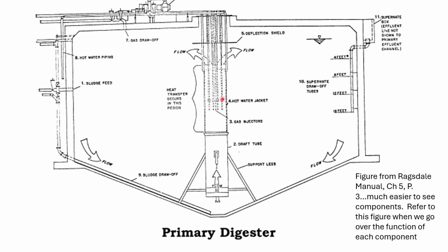Okay. But we also have a heat exchanger here, and that heat exchanger is what's keeping us at our optimum temperature range. But remember, if we misoperate this and we go above 130 degrees Fahrenheit, what's going to happen is this sludge is going to cake onto the heat exchangers here, and the sludge out here, further away from the center of our digester, it's going to cool down. And we're going to probably have that plus or minus 1 degree Fahrenheit exceeded fairly rapidly, and that would be caused by misoperating the